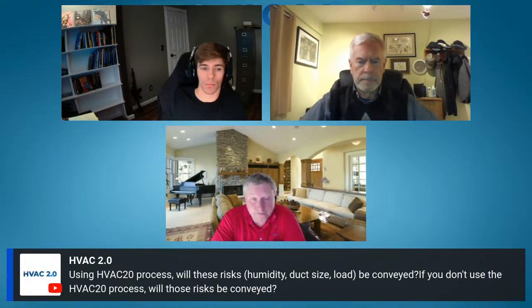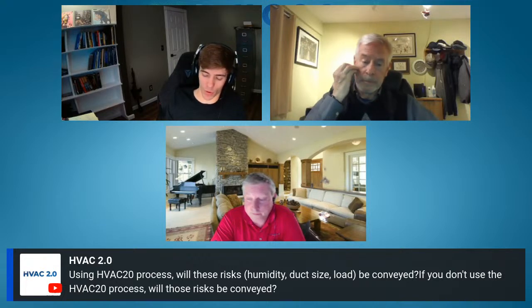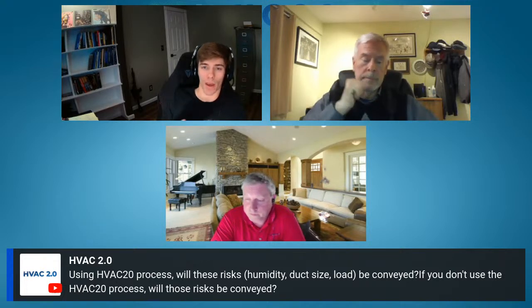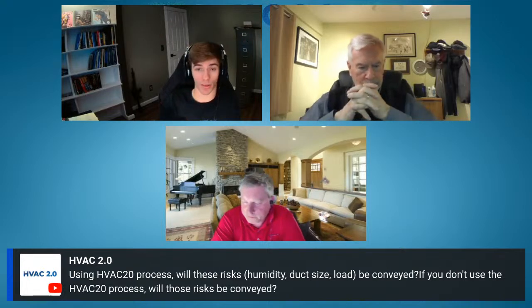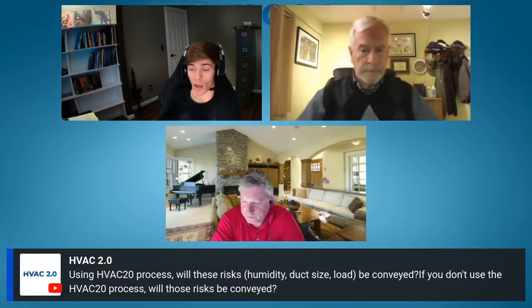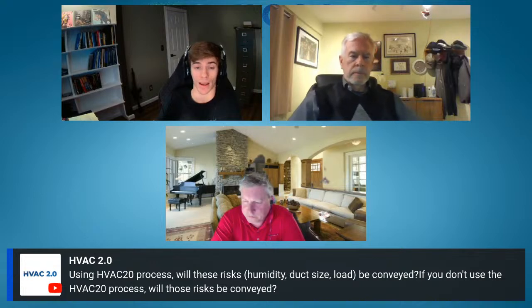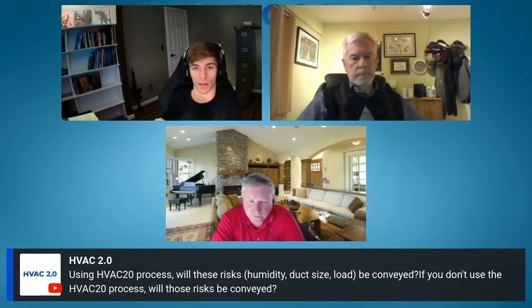What it comes to, another thing that I don't think a lot of people do is lay out, okay, if we do X and Y occurs, then the next step is going to be Z. Such as, if I was in that situation, and somebody was dead set on a 4-ton system, and I put that system in, I'm going to leave them with a couple of cheap hygrometers, and I'm going to say, hey, this reads out humidity.